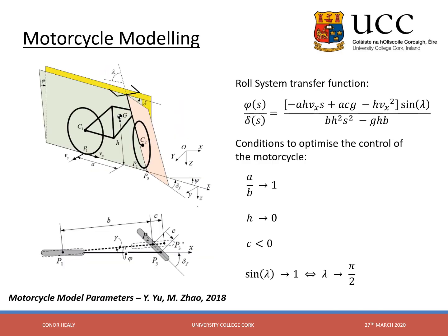In this project, a model-based design approach was used. This meant that instead of designing a motorcycle, building it, and then trying to control it, the motorcycle was designed with control in mind from the beginning. Such an approach always starts with a mechanical model. Here you can see the transfer function for the roll dynamics of the motorcycle.